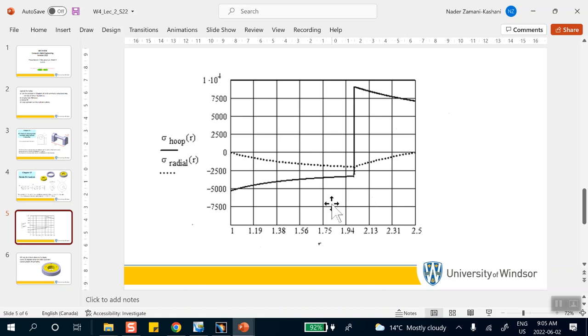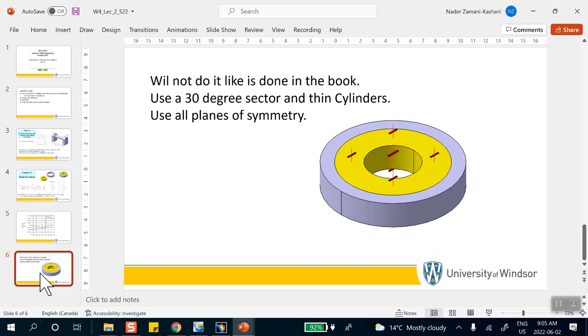Okay, so what we do in that particular case, we take a slice of this long tube. As long as that slice is not too close to the end, they do behave the same way. They actually don't elongate that much. So here's the story. If I have tubes shrink fitting inside of one another, all I need is to take one slice. The top is on roller, the bottom is on roller. This is not because of symmetry, because this whole thing is the same unit-wise as you go up the tube, they all behave the same way.